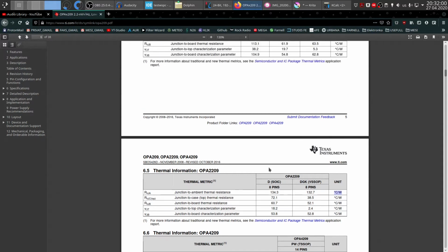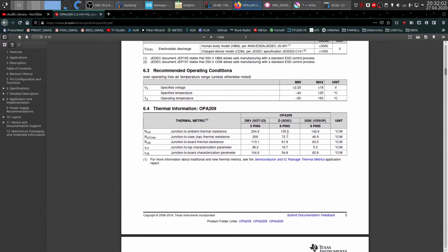Therefore, when you have only one amplifier per case, you can see that the thermal resistance is the same, but now you only have one that's wasting power, therefore the temperature increase of the package will be smaller. So that's a more logical way of explaining why we should use a single amplifier package instead of dual.